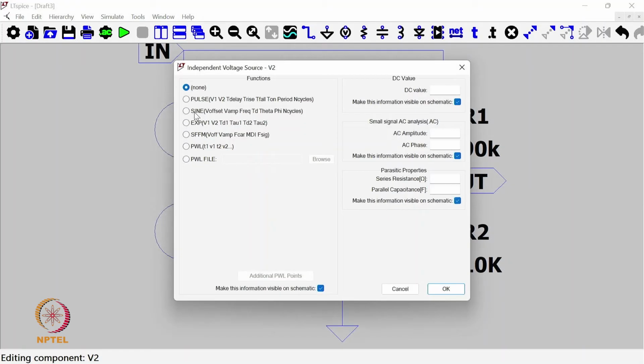So we go to advance, we take the sine signal itself. Now the noise does not have any DC value, so we put DC 0. Amplitude is, let's say 2 volt. However, this is very high, but just to see the noise is there, we apply 2 volt of noise, and frequency is, let's say 100 kilohertz. So the frequency is very high because it's a noise.